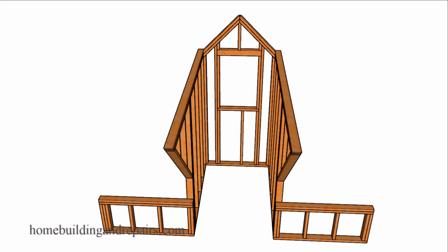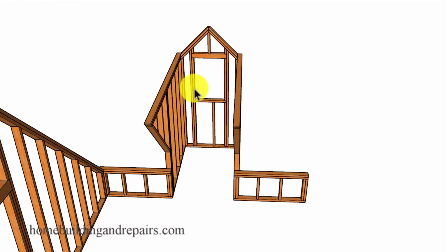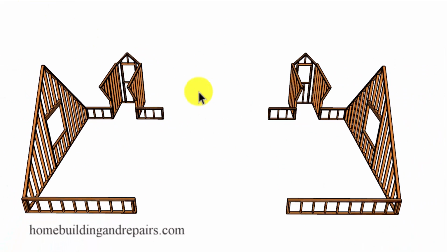And some of these sections might be a little easier to build after the roof is built. I don't expect you to build this section right here before the roof framing has been installed, but that doesn't mean you can't extend the top plates out a little bit so that they can be cut off later.